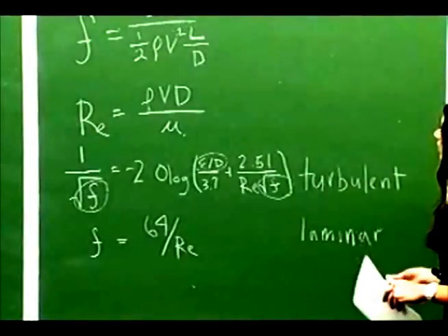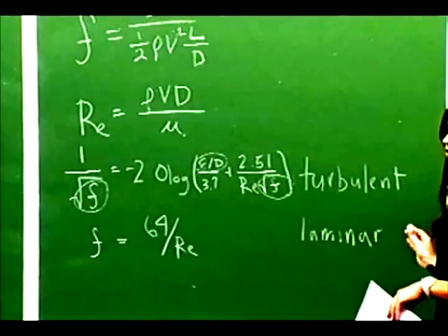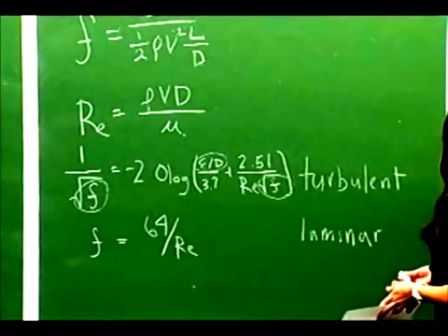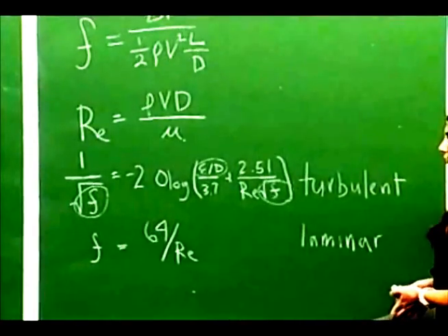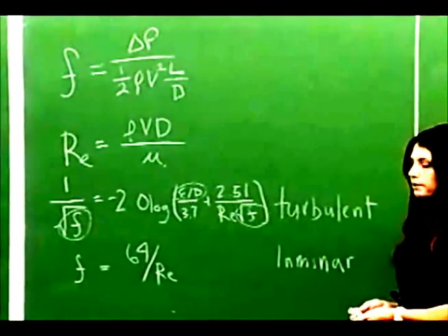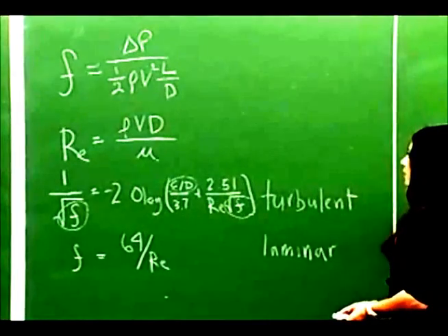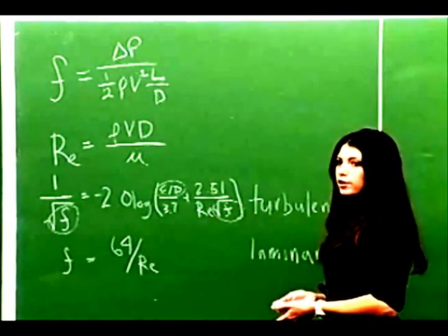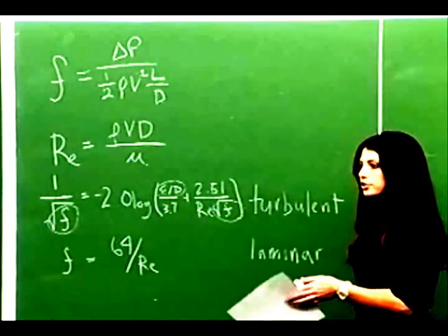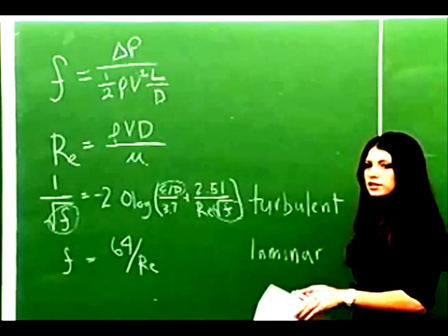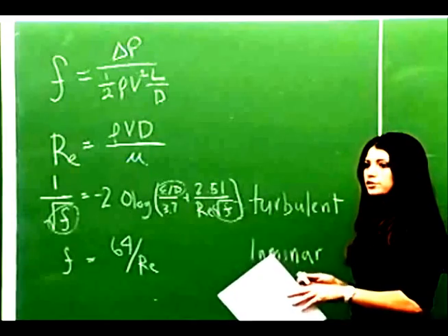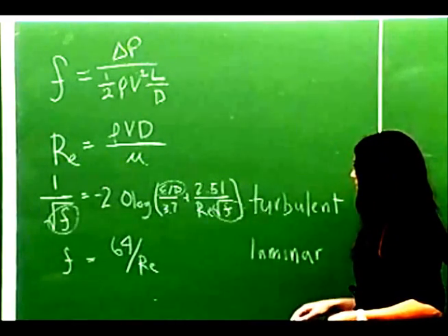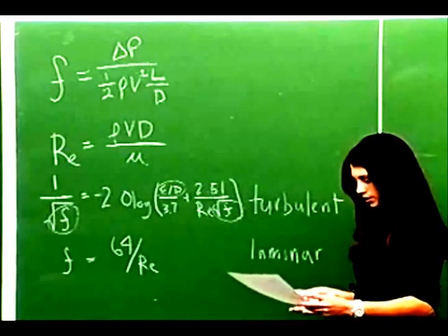Okay, so these will be used for your major losses, which will be the length of pipe that you'll be looking at. So in the experiment, as you'll see in the experiment video, there are two major losses that you're looking at, and then there's a minor loss due to the elbow. So the major losses are just the frictional effects that the piping system sees due to the length of pipe that the fluid is flowing through. And that's what you will use these for.